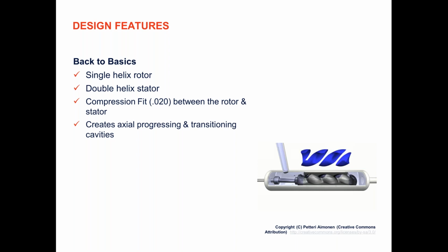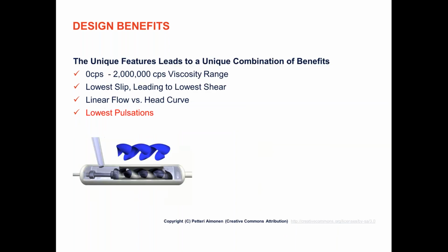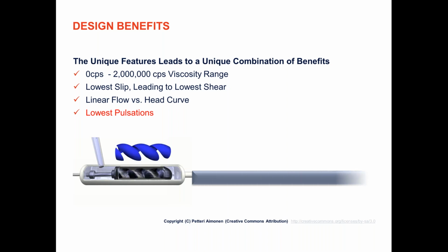Again, the pump works exactly the same as its larger pumps that we discussed earlier for sludge and for cake. There's a compression fit extremely tight between the rotor and the stator. Because of that compression fit, this style pump has the lowest slip on the market out of all pump technology. Low slip is a direct relation to low shear, which is why if you look at most polymer systems at wastewater plants, they will have a progressive cavity pump moving that polymer.